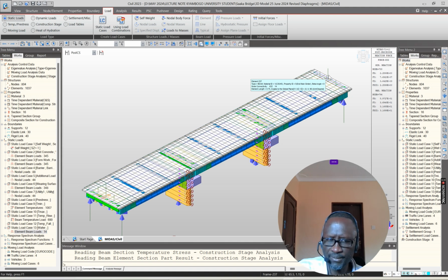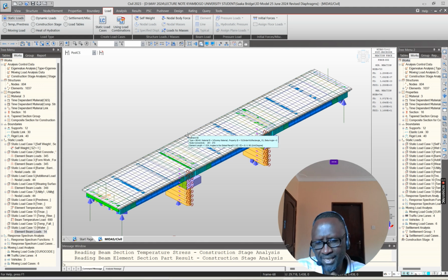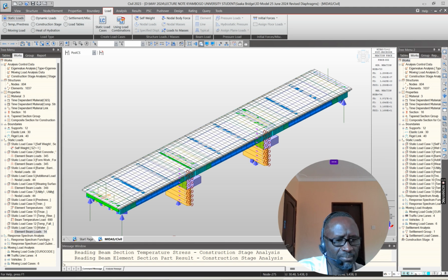And also I think you make the assumption that the end of the pier cap is square, so that the factor is higher. Otherwise, if it is shaped like a triangle, then the factor tends to go on the lower side. But we don't have control in practice over what happens when water is flowing. Sometimes it flows with trees, so you have to be careful. So as an engineer, a slightly higher value will give you some comfort and you can afford to sleep.